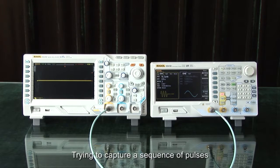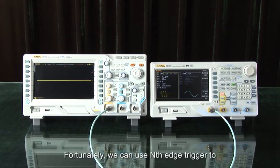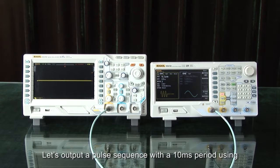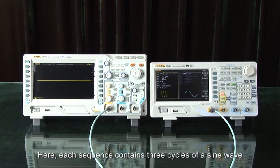Trying to capture a sequence of pulses with standard edge triggering modes can be difficult. Fortunately, we can use nth edge trigger to make this task quite a bit easier. Let's perform a brief experiment. Let's output a pulse sequence with a 10 millisecond period using a RIGOL DG4000 arbitrary waveform generator. Here, each sequence contains 3 cycles of a sine wave.